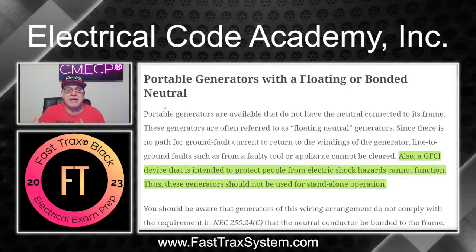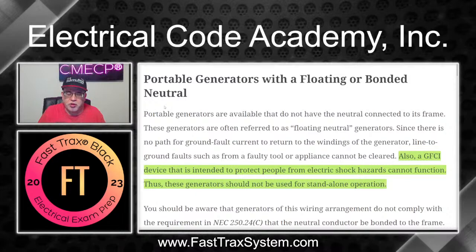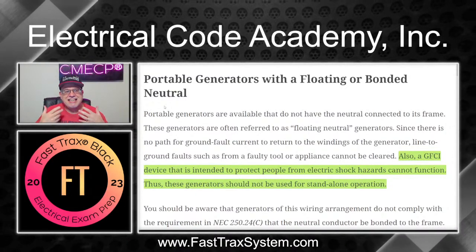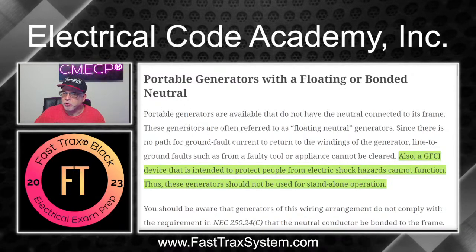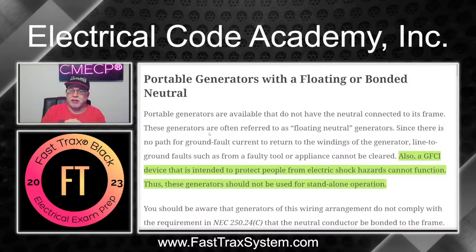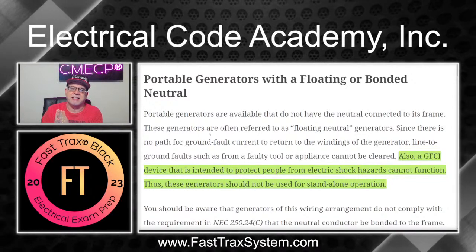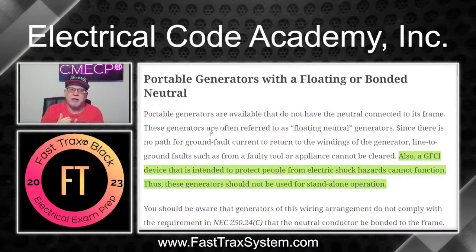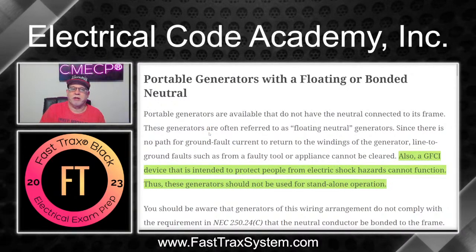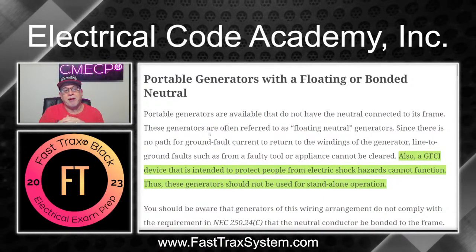Okay. Now, that doesn't mean that you're not going to overload and trip an overcurrent device, but I'm going to show you how it really can happen when it comes to the floating neutral. Now, that doesn't mean that it's not going to work and you're not going to plug an extension cord into it and you're not going to get power. Obviously, you are. But when you need those devices to function safely and clear a fault, then that's when the problem occurs. And you might say to yourself, well, I've never tripped a breaker on my floating neutral generator. There's probably a reason why that hasn't happened, okay?